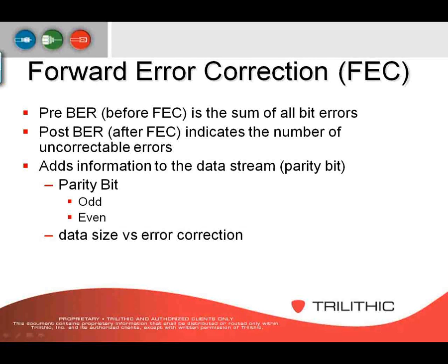Now, pre and post forward error correction measurements. Digital communication systems include the means to patch up some of the bits that become corrupted in a transmission, and that's what the forward error correction does. The forward error correction data included with the QAM data transmission is the information the QAM receiver, or your digital set-tops, use to fix the misinterpreted bits.